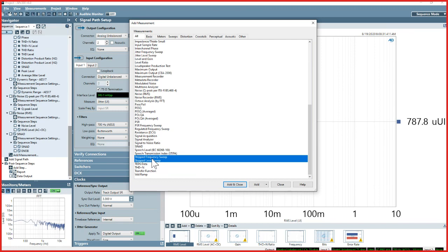You could use the ASIO interface potentially to bridge across to USB, or you could use what we would refer to as open loop test, where essentially we would record or play back WAV files and then analyze those WAV files. Those are both potential solutions to that problem.